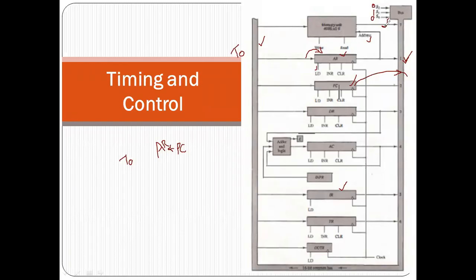For placing this onto the common bus, you have to select the memory, so the 111 select lines have to be set. This 16-bit information is now placed onto the common bus, and it needs to be accepted by the IR register. So you activate the load control signal of IR, so that the 16-bit instruction code is copied onto IR.